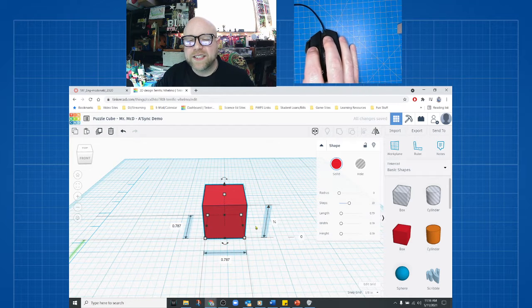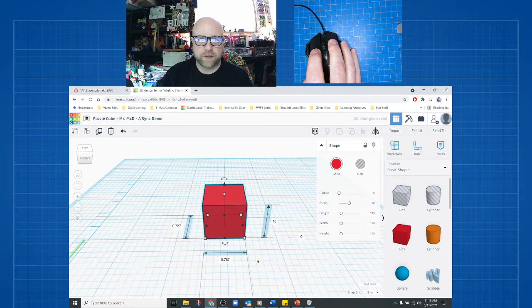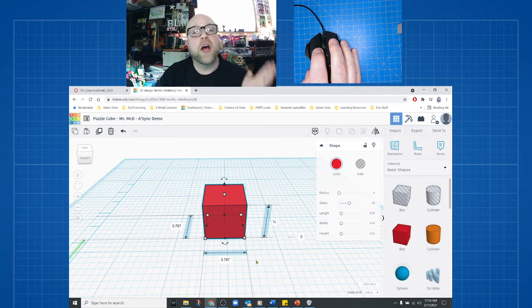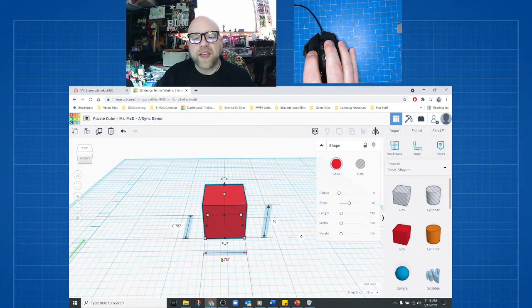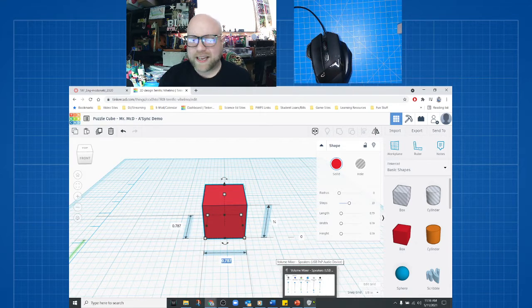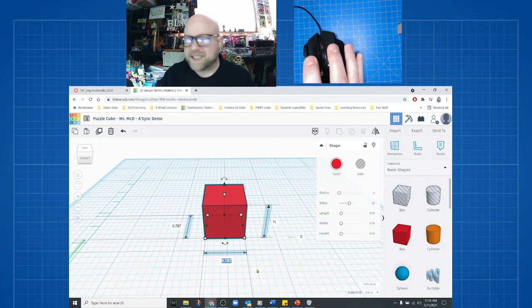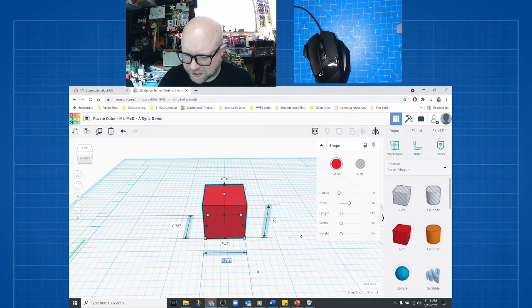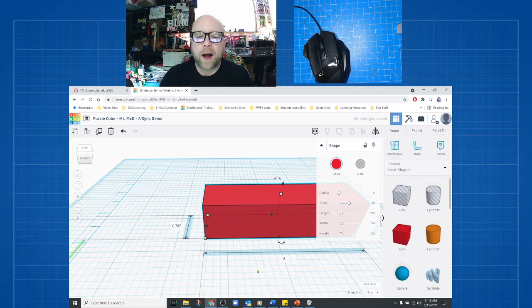Now, the way it's going to display it is 3/4. 0.75 is the decimal equivalent of 3/4 in fraction, the same as 75% in percentages. They're all equivalents. The weird thing is, if I click in this space and think to myself, well, it's displaying as 3/4, so why can't I just type 3/4? Would make sense, right? The problem is TinkerCAD only accepts decimal values.